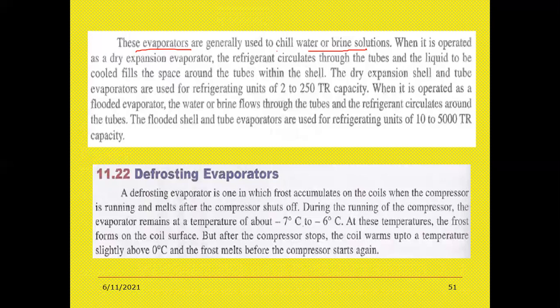During the running of the compressor, the evaporator remains at a constant temperature, about -6 to -7 degrees centigrade. At these temperatures, frost forms on the coil surface. So whenever the temperature is about -6 to -7 degrees, at that point the frost will be on the coil surface.